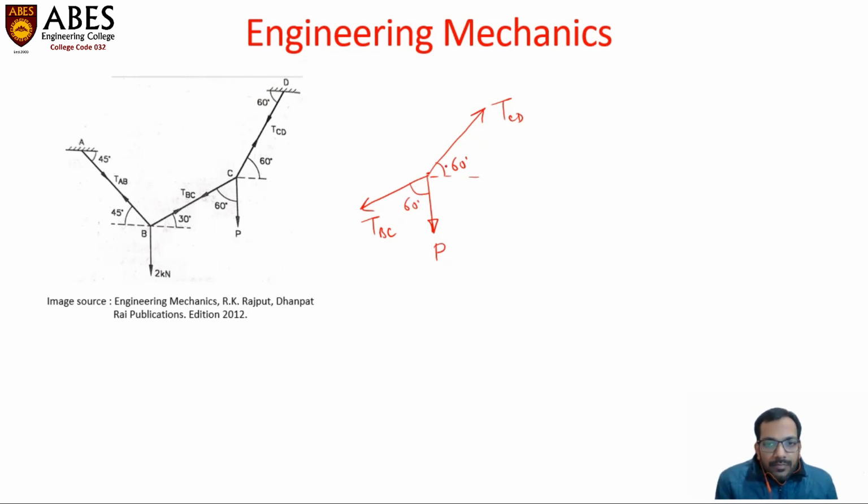And once again, we are going to apply Lami's theorem because TBC is known now and we can calculate the value of TCD and this unknown force P.